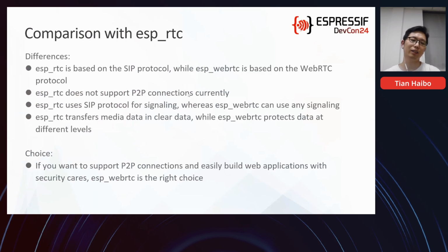Another difference is that ESP RTC transfers media data in clear form, while ESP WebRTC protects data at different levels, as previously mentioned. As for the choice, if you want to support P2P connections and also easily build up web applications with security, I think ESP WebRTC is the right choice.